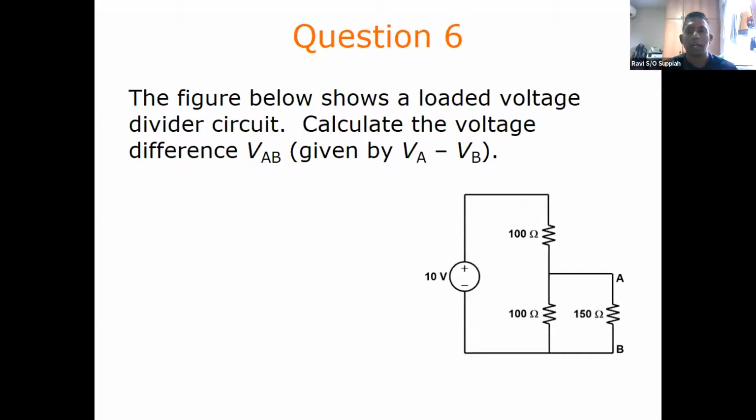So this next question here is on using Kirchhoff's voltage law. Here, we are supposed to calculate VAB, the voltage across this. Now, the voltage across A and B is the same as the voltage across this 100 ohm, because this point here is also A, and this point here is also B. They're both the same. Now when current flows out of the supply voltage here, it will come here and split into this branch and this branch, and then it will come back again towards the supply.